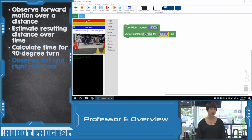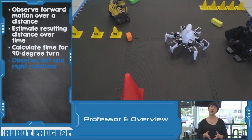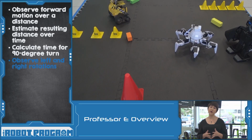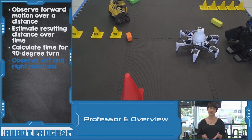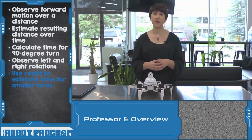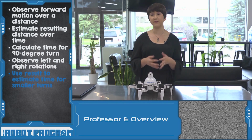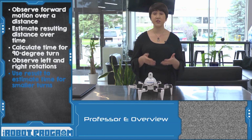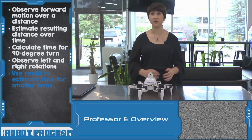Again, click the green Start button to execute your code and see how long it takes your robot to move 90 degrees. You will now have a rate for your robot's turn movements, how many degrees it can move in a certain number of seconds. Use this information to extrapolate for your other turns. Maybe you only want your robot to move 45 degrees. You just have to divide that time value by 2.